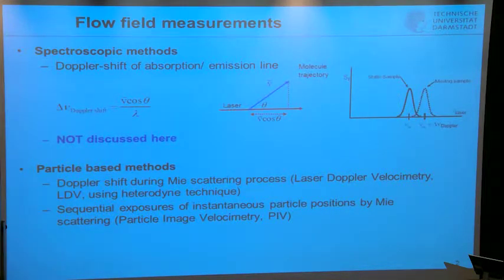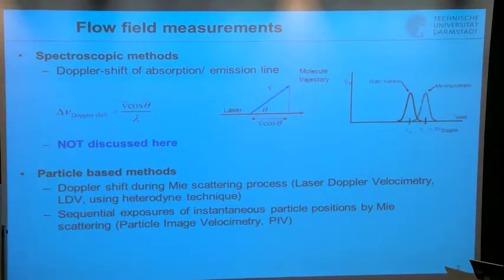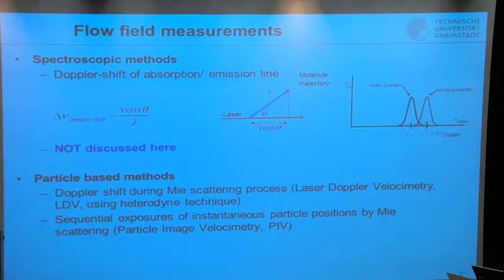And by my own experience, you need not only time to resolve that line profile precisely, which you do typically in a line scan, but as well a certain minimal velocity magnitude, such that you can distinguish these peaks. For gaseous flows, using NO as a marker, that is in the order of 30 meters per second.